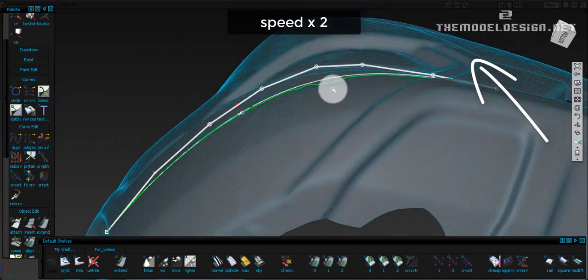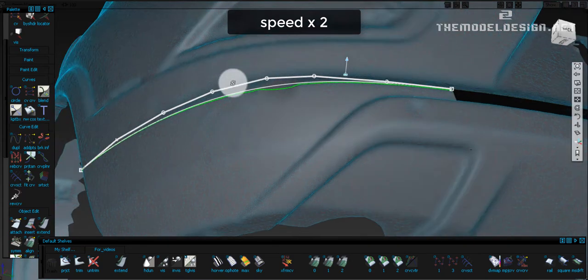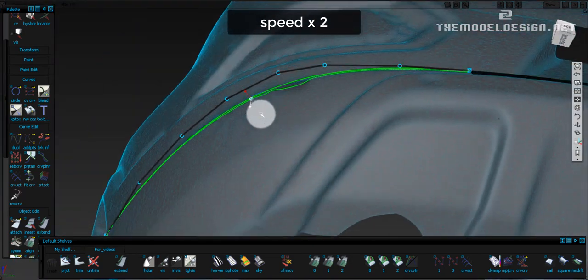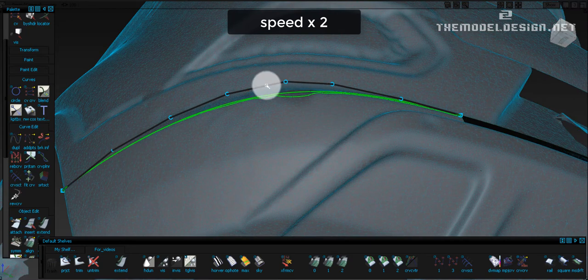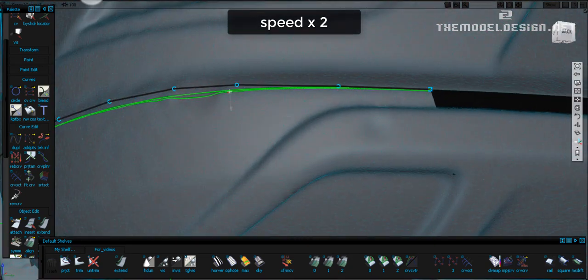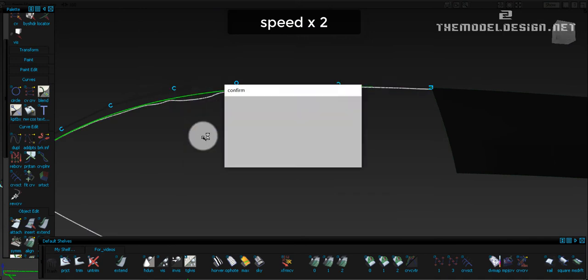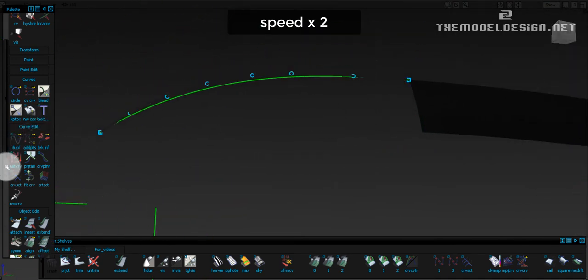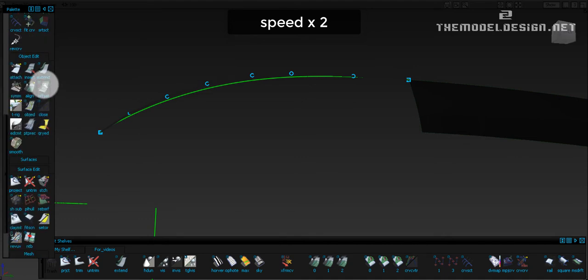Reverse engineering has this attribute that you always end up with heavier geometry, as if you were to model it off the blueprints or photographs. Because staying true to the scan requires more sculptability and accuracy, and therefore more CVs. But after all, just remember, you need to do whatever it takes to achieve the shape, and adding more CVs will help you with achieving that.